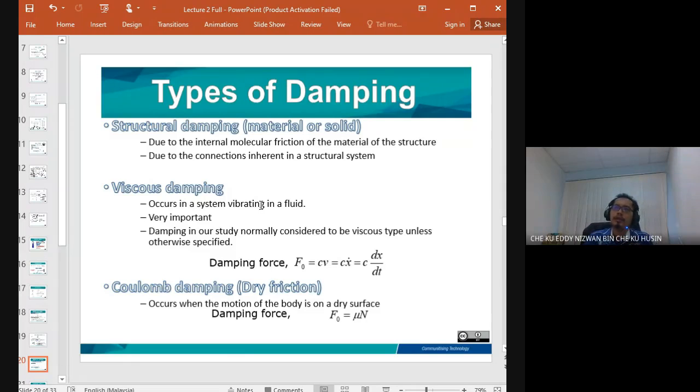And the same goes for machinery. If your machinery has a high vibration issue and you don't know how to solve it, having already controlled the speed and the structure and still having high vibrations, then for that kind of solution you can add another damper, or what we call an isolator, with a certain amount of damping to absorb the vibration. The same goes for the engine mounting in a car, ensuring that the vibration of the engine doesn't transmit to the car body.